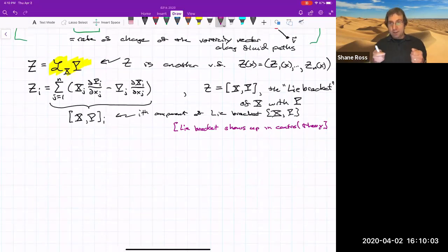Like for a car, I can go forward and backward instantaneously, and I can steer. So how is parallel parking even theoretically possible? I can't instantaneously move sideways, but by combining going forward and backward and turning, I am able to go sideways. And calculating the Lie bracket of forward, backward, and steering vector fields would show that.